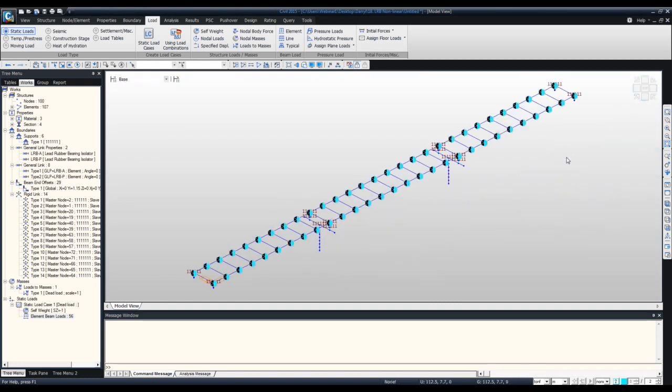So there's a couple of important things to remember. First off, unlike linear analysis, the principle of superposition does not apply to nonlinear analysis. This is very key. So this example pertains to analysis for both dead load and seismic load, but it is not correct to linearly combine the separate results due to each load afterwards.